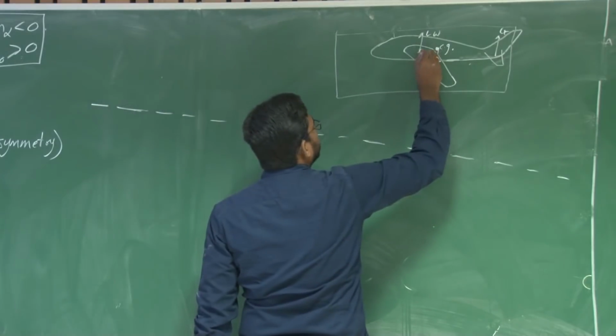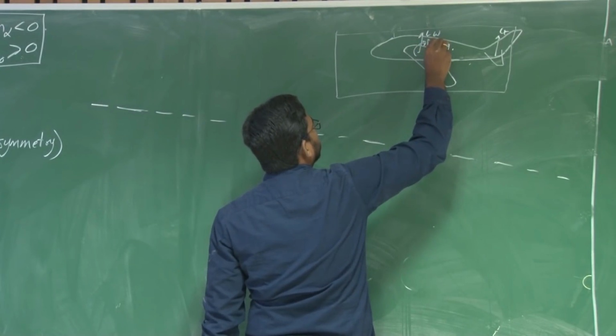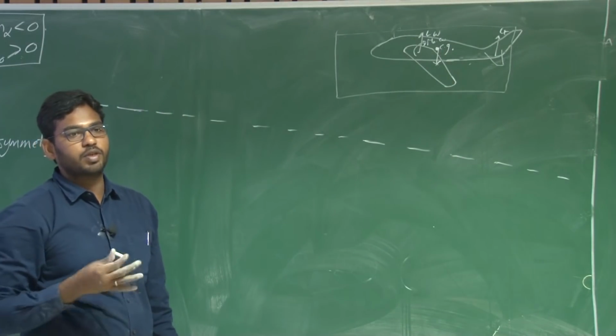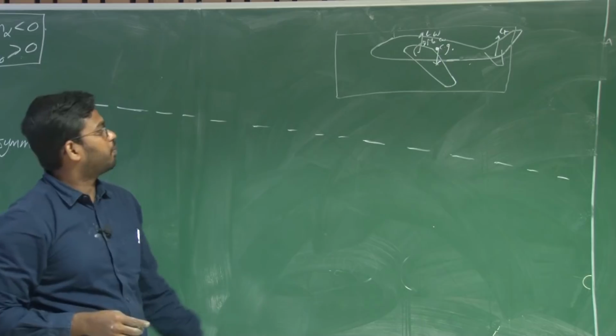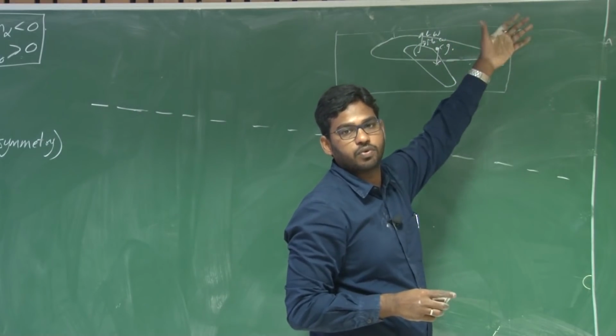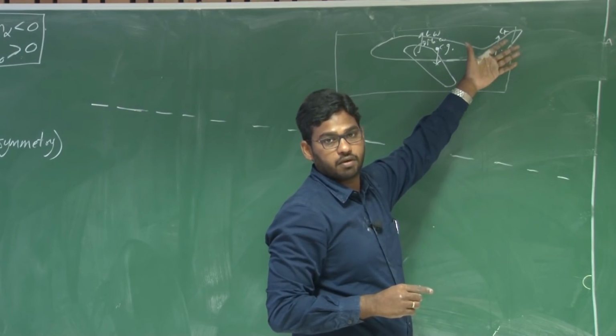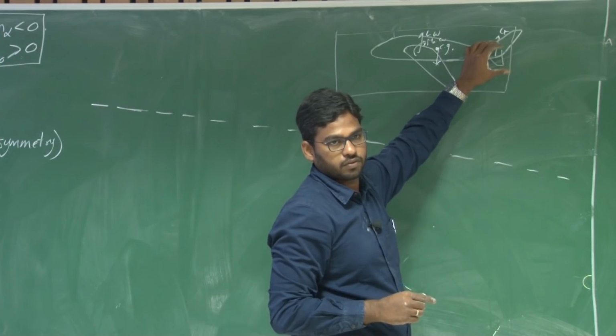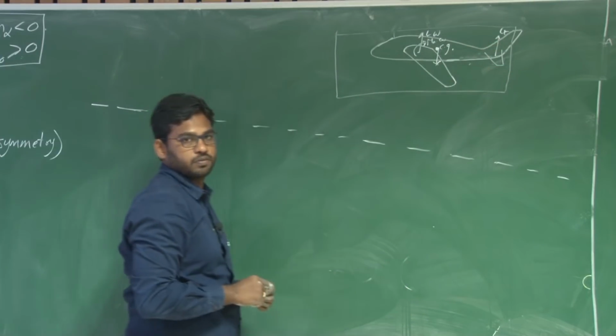And say you have a pitching moment about the aerodynamic center of the wing. Generally the tail is a symmetric aerofoil. The purpose of the tail is to create a moment rather than a greater force. It creates a moment by generating a smaller force about the CG.